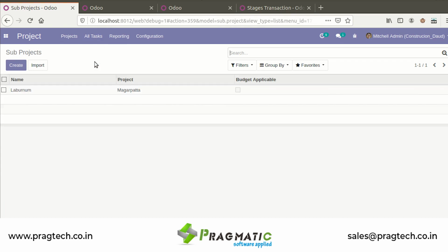Now we need to create the different sub projects. What happens is, against any one construction project, there can be so many sub projects. Suppose I have created the Amanora project, so under that there might be a commercial project as well as a residential project. So for that we have a type of sub project that we can mention here under one project.